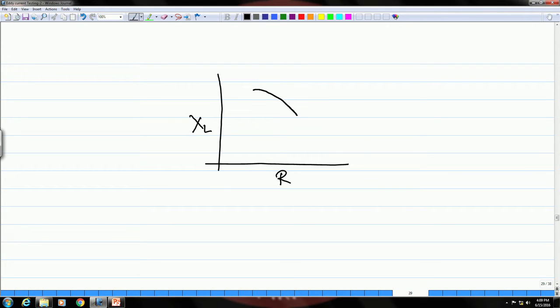So, let us say you start increasing the thickness in this manner by adding, let us say this is the first sheet, and then you are adding the second sheet, third sheet, and so on. As you keep on adding the sheets of brass, the thickness will increase, and this is how the thickness curve will be with respect to the eddy current. And at some point you will see that the variation in the impedance of the coil will stop, and it will become independent of the thickness.